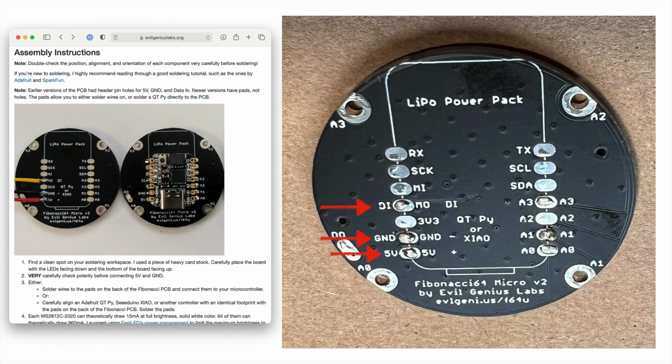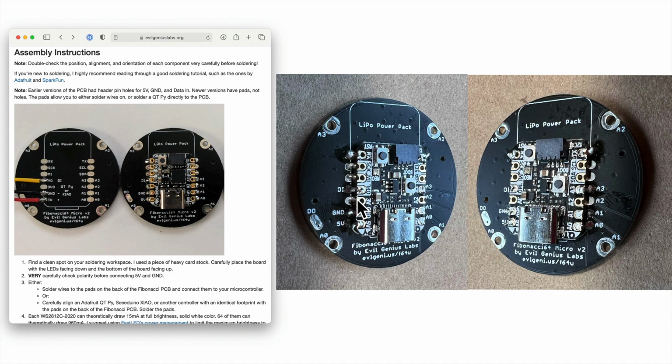So back to my very simple quick demo. First, I soldered up my QT Py. This technique should be the same for any board with a QT Py form factor. There are 3 pads that you need to solder to get the lights working: M0, ground, and 5 volt. Before soldering, I tinned these pads, then taped the QT Py to the Fibonacci to hold it steady, and then I soldered the 3 main pads, plus a few other pads to make sure the connection between the board and the Fibonacci was nice and secure. As you can see, I continue to be genuinely terrible at soldering.